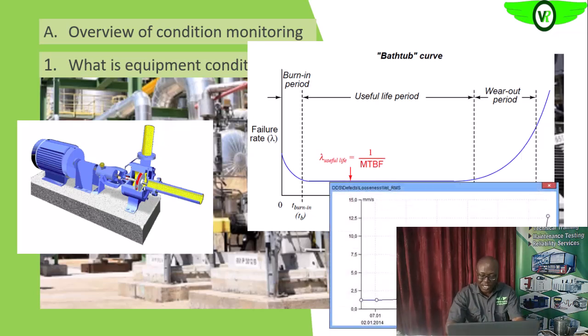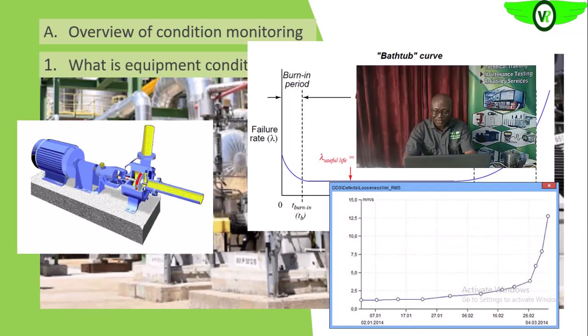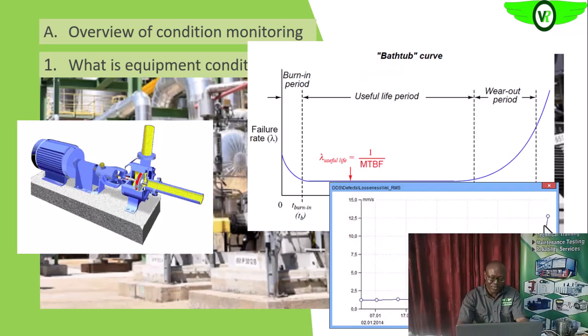As you go out, you take your readings of that particular parameter, be it temperature, vibration, or even pressure. As you are logging, and as it is increasing, you'll be seeing it. This will give you a visual representation of what is actually happening as that condition deteriorates within the component.